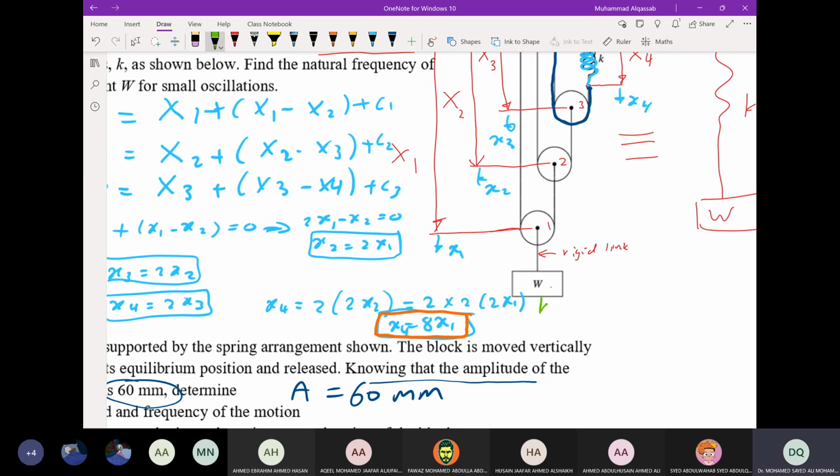which will carry the weight. So this is the weight, and the link will have the weight. If you take the free body diagram of the pulley, there will be weight here, and the tension in the cord will be W over 2 and W over 2.